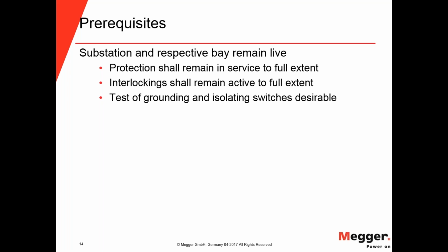Since the bay is in service, you need to have all the protections still working to full extent. And the same with interlockings. They shall remain active to full extent, so to prevent operating these connectors in the wrong way, for example.